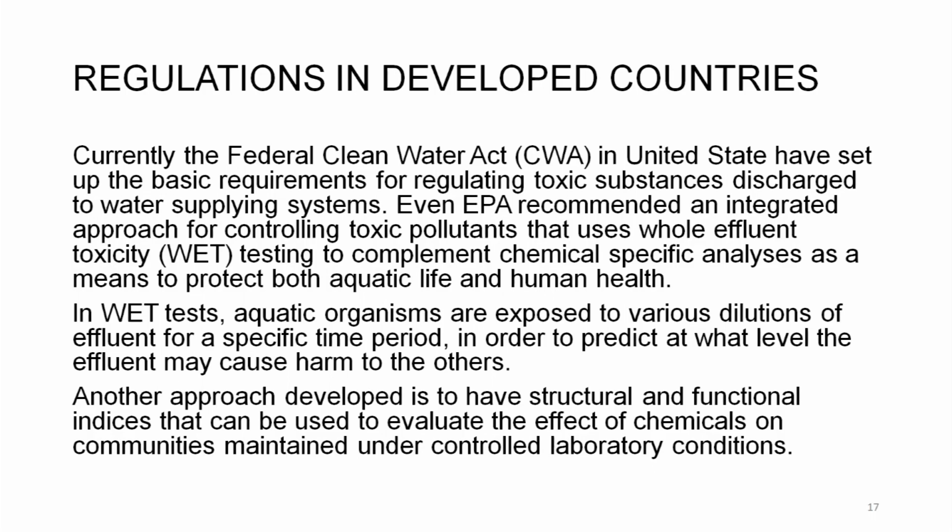In the whole effluent tests, aquatic organisms are exposed to various dilutions of effluent for a specific time period in order to predict at what level the effluent may cause harm to the others. Another approach developed is to have structural and functional indices that can be used to evaluate the effect of chemicals on communities maintained under controlled laboratory conditions.